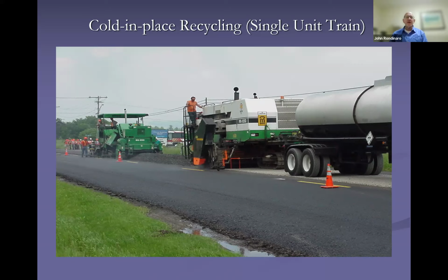You can be adding in extra emulsion. You can be adding in aggregate or stone. And in this case, they're laying out a windrow into this windrow paver, and that's going to be laying down your new, essentially, binder course or base course.